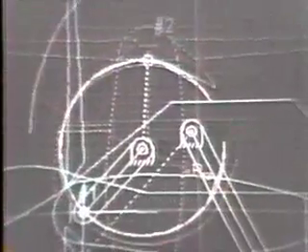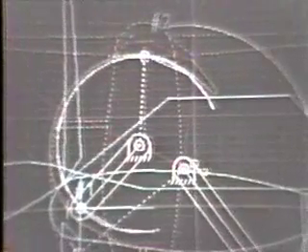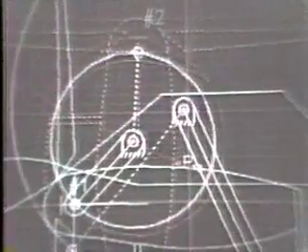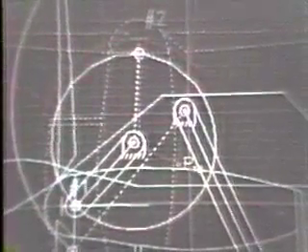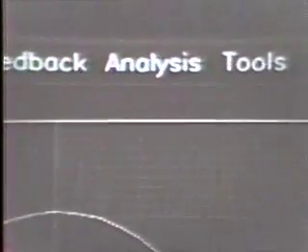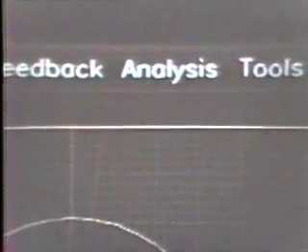As the designer positions the joints for the mechanism on the screen, the complete coupler curve for the mechanism which is being instantaneously displayed is shown with red and green branches indicating the two modes of assembly for the mechanism, or the various lockup positions for the mechanism.